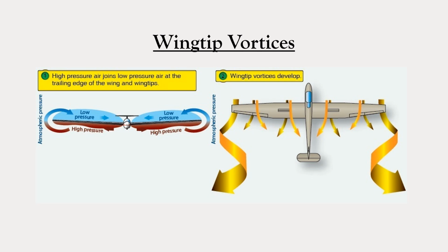The effect of that is that there's this circulating air behind the aircraft coming from its wingtips. That vortex is going to be behind, and it tends to flow down. It's deflected down just like the rest of the air that the wing is influencing. When you box the wake, you're encountering these wingtip vortices from the tow plane.